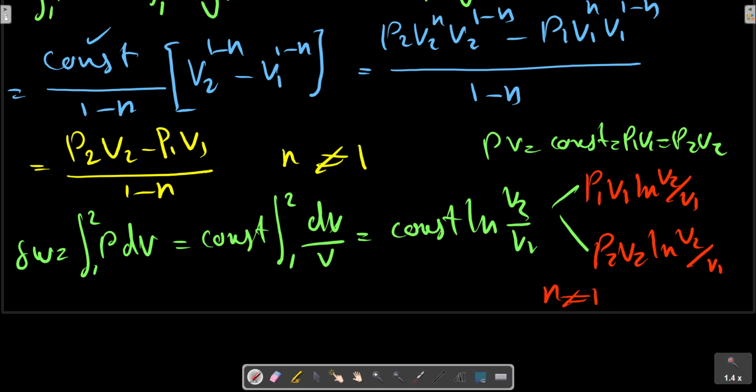Note that in these two equations, we did not say that the work equals the expressions given in these equations. These expressions give us the value of a certain integral. That is a mathematical result. Whether or not the integral equals the work in a particular process depends on the result of thermodynamic analysis of that process. It is important to keep the mathematical result separate from the thermodynamic analysis, for there are many situations in which work is not given by this integral.